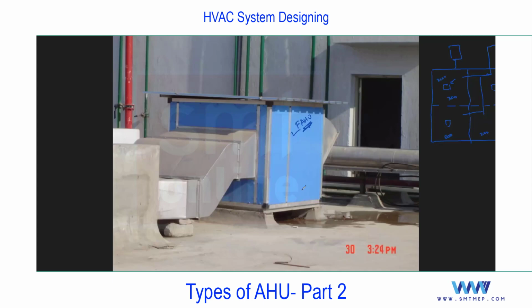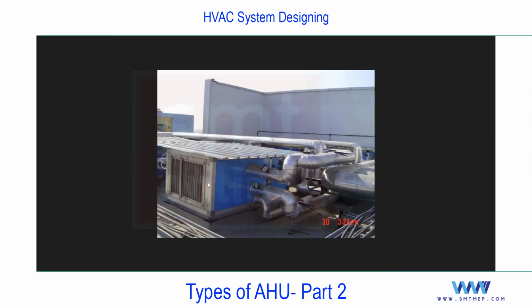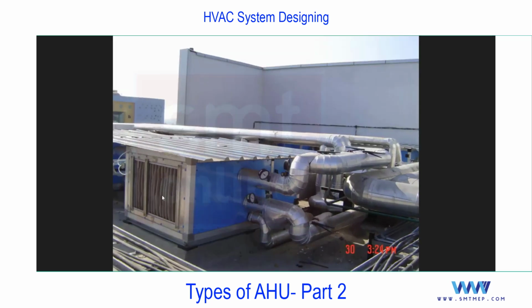And since we are placing it completely outside, this must be what? Double skin. If you're using it in India, simply we connect a coil piece like this. But if you're using this in the Gulf, we require a sand trap louver. Here at the suction side, this picture is taken from a project in Hyderabad, India, so you can find the filter. But if this project belongs to the Gulf, you can find a sand trap louver here.